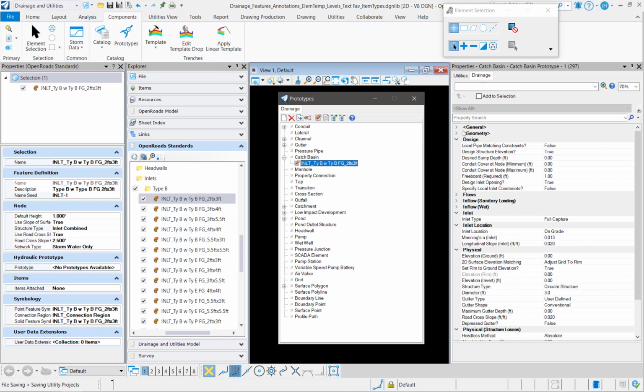properties. Now I've already collapsed the areas that I don't need to configure for the prototype. Remember, what we're doing with the prototype is we're setting those initial hydraulic settings. So we want to set these in a way that is going to fit most purposes, and then after placement of these nodes or per project, these could be changed as needed.